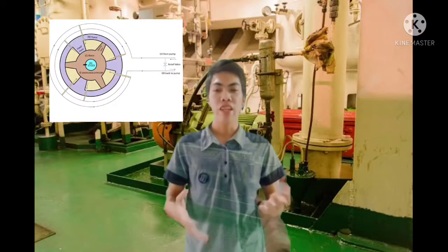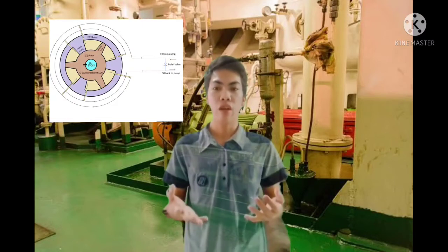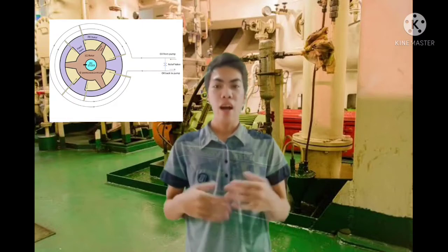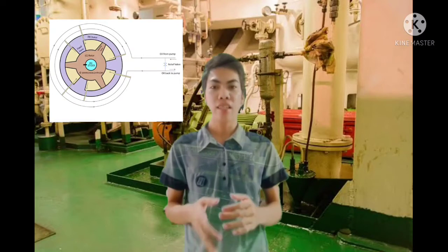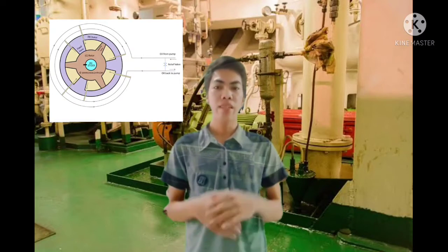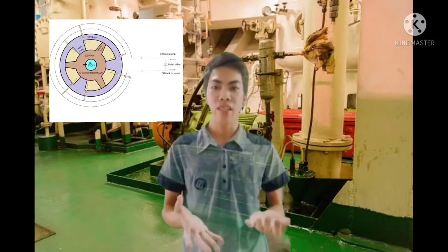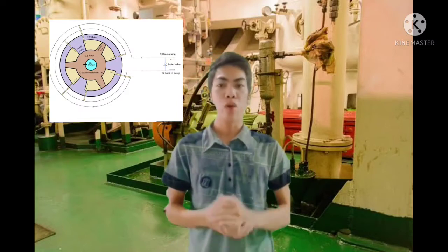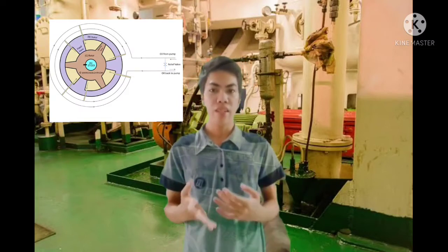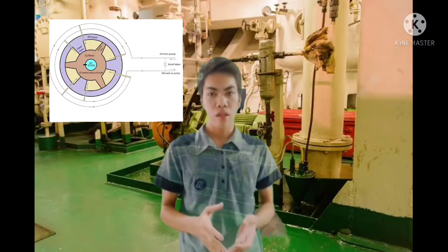So second is the rotary vane. Rotary vane: spinning rotors are off-center, with arms of self-adjusting length. Air fills the cavity and travels around. Air pressure goes up, and air is forced through the output.